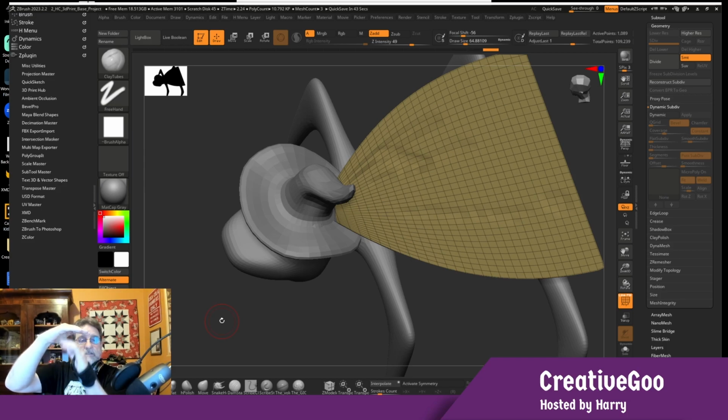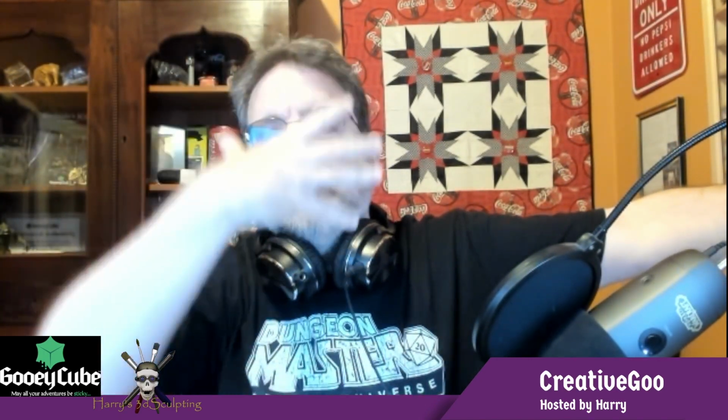But in all of those cases, if my arm is out like this, I don't know if you can see. Let me get rid of the screen and come back to me. So if my arm is out like this across the microphone, right, and I print, well, if I'm starting from my head, I can print Harry's head pretty well, but where's the arm going to print from, right? So between the build plate and my arm, there's empty space. And so that's what supports do, they basically print material up until it reaches the arm, and then it starts printing the arm, so it's supported.